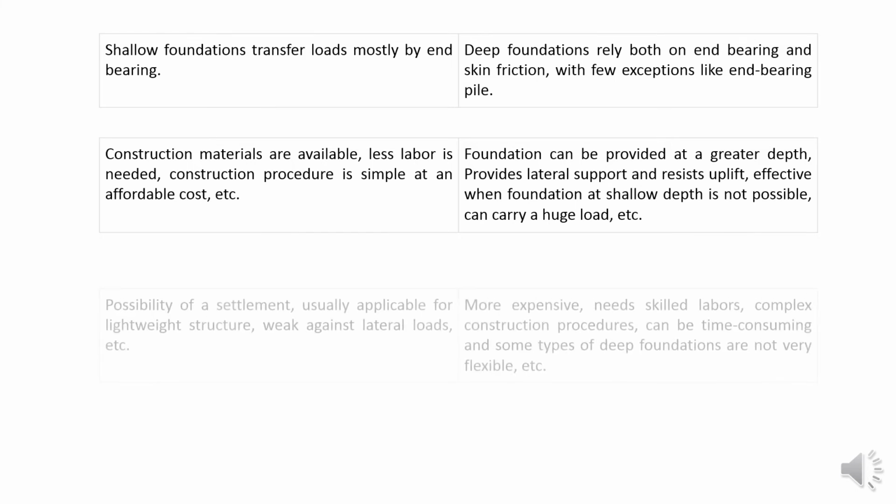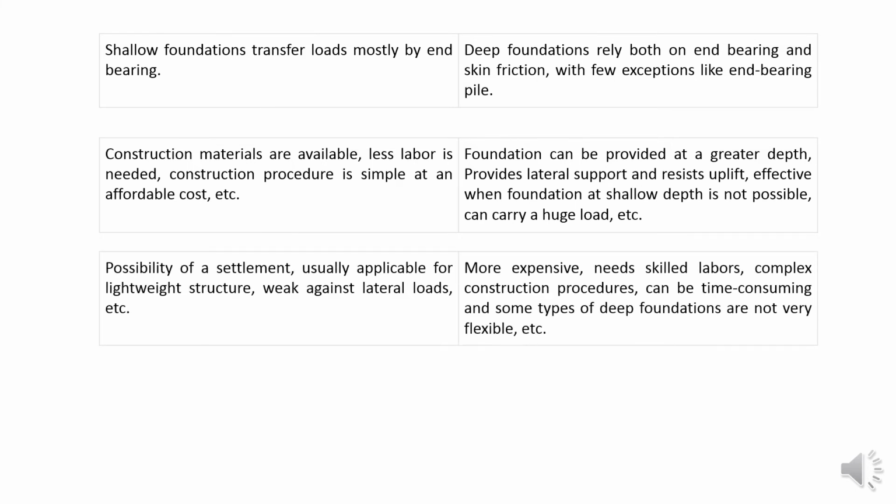Some of the disadvantages of shallow footing: the possibility of settlement, usually applicable for lightweight structures, and weak against lateral load. In a deep foundation, some of the disadvantages are: more expensive, needs skilled labor, complex construction procedure, can be time consuming, and some types of deep foundation are not very flexible.